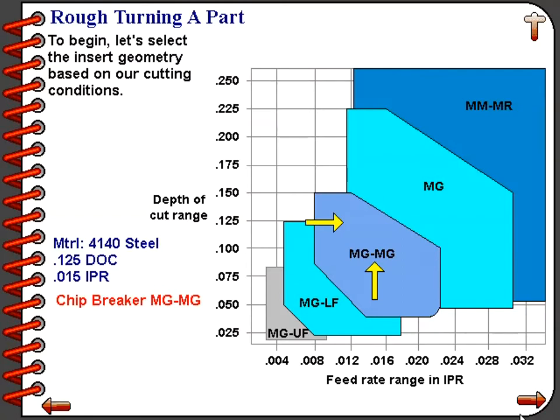If you think you can take a heavier cut, first increase your depth of cut, and then once you achieve the maximum depth of cut that you feel safe with, you can slowly bring up the feed rate to the point where you are still feeling safe, but yet still machining very efficiently.